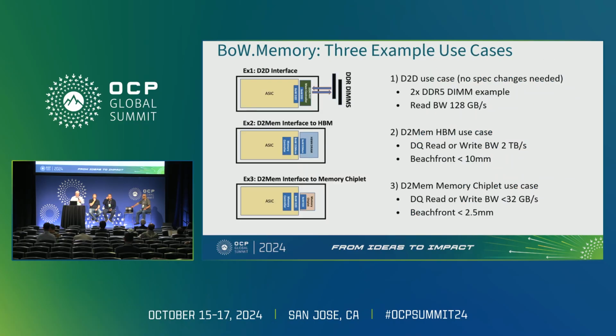In our working group here, we came up with 3 use cases that we're focused on. The first here is just a discrete memory chiplet, if you will, that talks to third-party memories, such as, let's say, an off-package DDR or LPDDR. And this is really a logic-to-logic interface then. So something like UCIe and Bunch of Wires, as they exist today, can do this, and in fact, there are already chiplets being built that have this function.